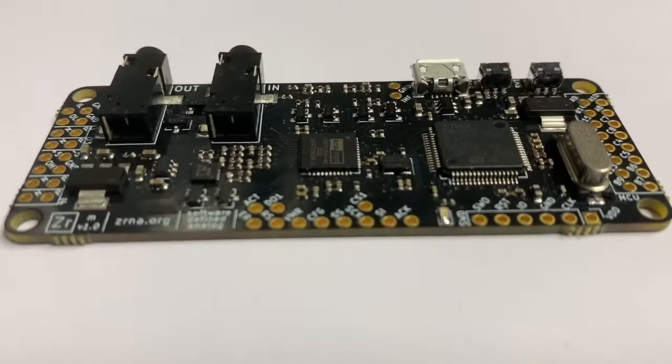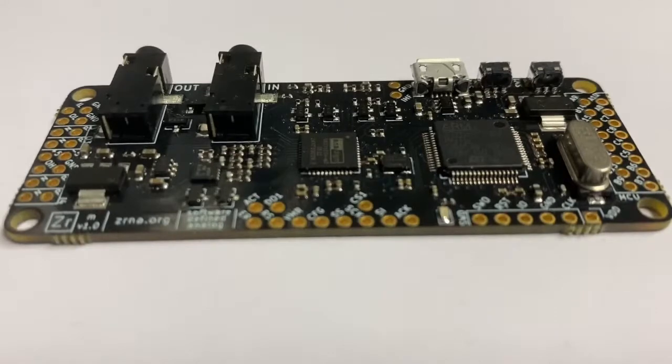This chip in the middle is made by a company called Anadigm and is basically a very simple reconfigurable analog computer on chip. It is not really well suited for solving mathematical problems, since the interconnect used by the manufacturer is based on so-called switched capacitors, so you lose one of the main advantages of an analog computer, namely continuous time.